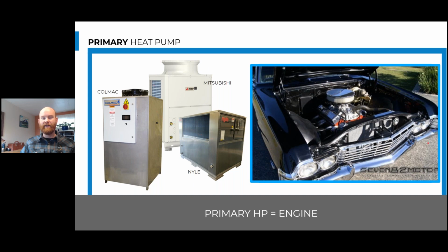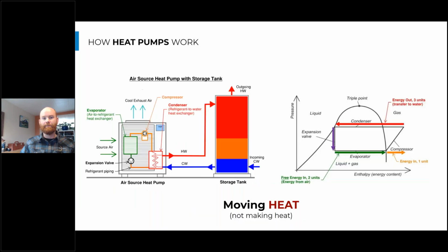And so our primary heat pump water heater is doing the big lift. It's taking that cold water in at 50 to 60 degrees from the city main connection and heating it up above 120 degrees, typically to around maybe 140, 145 to store in our primary storage tanks.